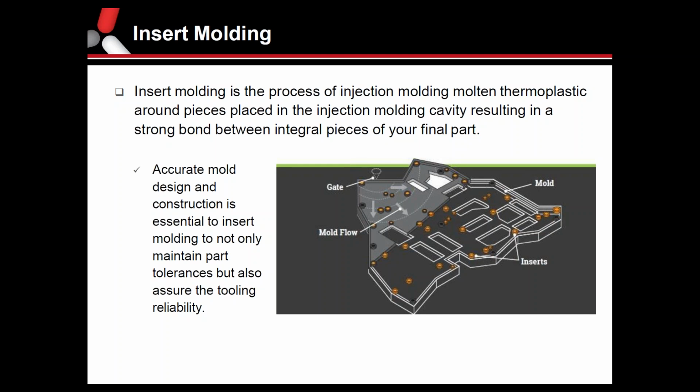That way you can run this tool. It does take a slightly longer cycle time as you have somebody loading all of these inserts into the tool. The tool is designed slightly differently to hold those parts in position so the injection pressure doesn't move them around. There's all sorts of things to consider when you're talking about overmolding metal inserts.